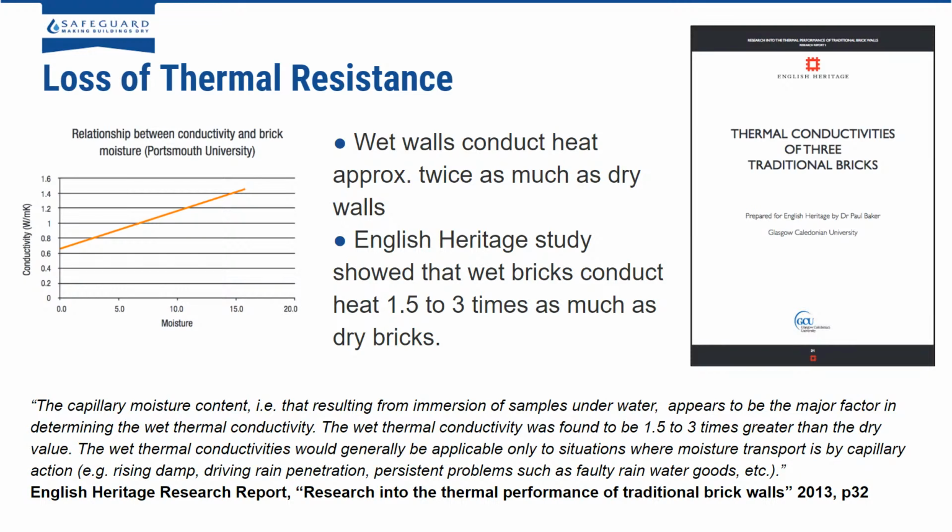Another factor which is not apparent visually, but in terms of your energy bills, is loss of thermal resistance. It's been researched by the University of Portsmouth that a wet wall will conduct more heat than a dry wall. That's effectively the same idea as where you put wet oven gloves on to take, say, a hot tray out of the oven.